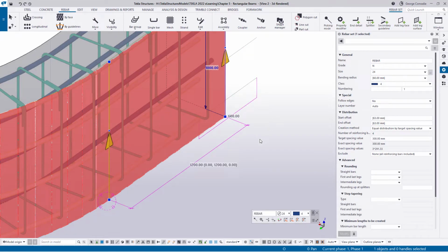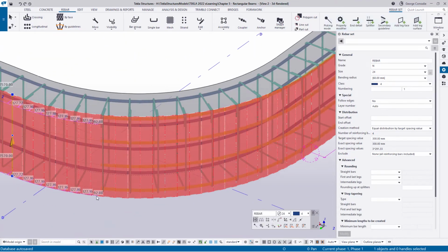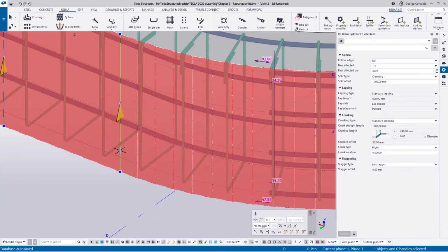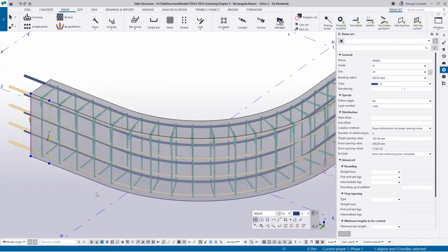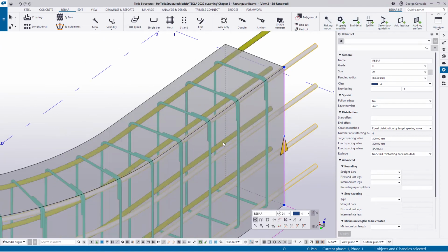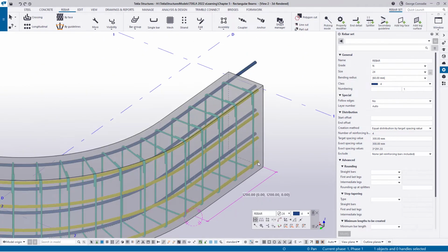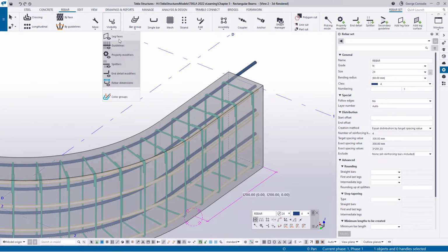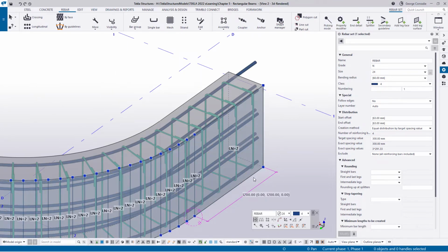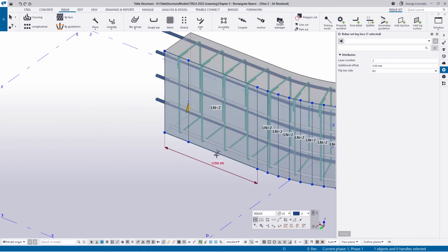and that's why it doesn't work. So what I'm going to do is, if I click here and I delete that split, and I click here and I delete that split, just to recover our bars, and also I'm going to delete this property, and I'm going to delete this property. So we're back to where we were in the normal. What I can do then is click on the bar, make sure our leg faces are on again, and I'm going to also select here and increase this to 1600, like so. And I'm going to do the same on this side, and I'm going to 1600 as so.